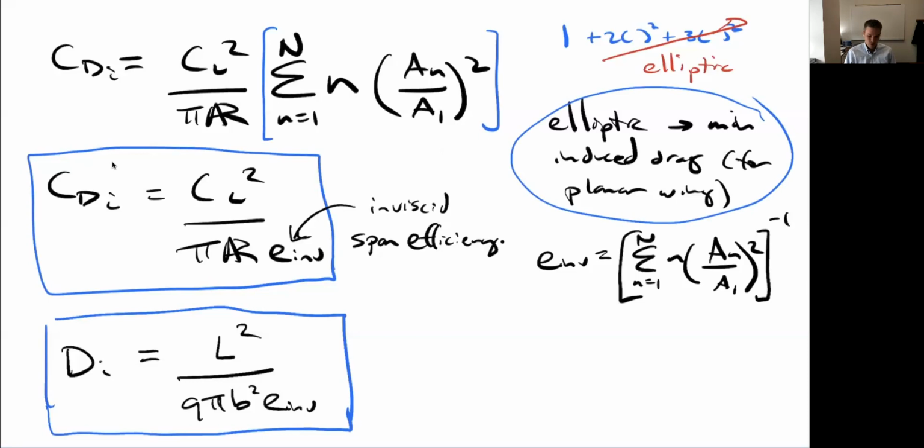One difference from thin airfoil theory is that in thin airfoil theory, we can compute each coefficient one at a time. So we can compute the first one and the second one, and then we could stop whenever it seemed like they were becoming really small and they weren't contributing much. In this method, they're all coupled, so we have to choose how many coefficients we want beforehand, and we have to solve them all simultaneously. We can, of course, redo that, but we can't just reuse the coefficients we already have. We'd have to start over if we wanted more coefficients and solve them all simultaneously again.